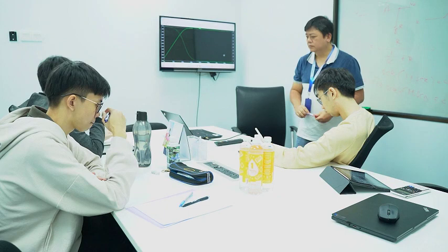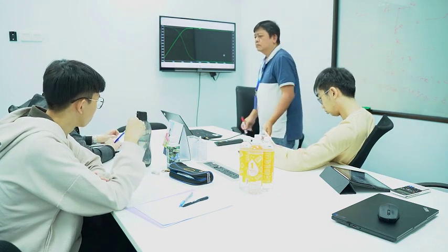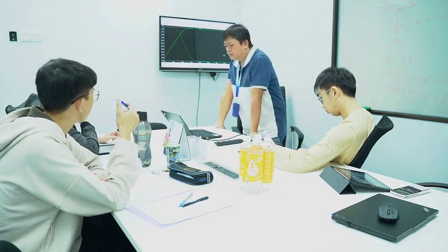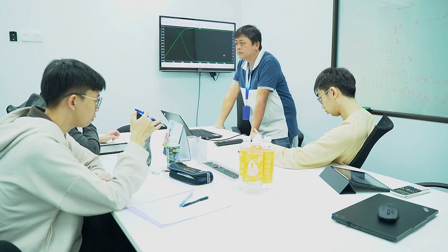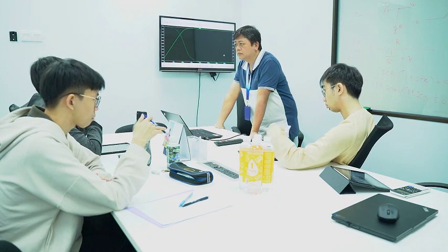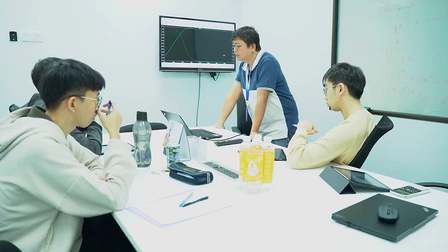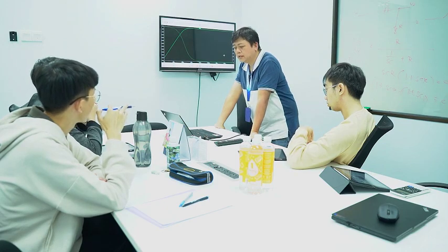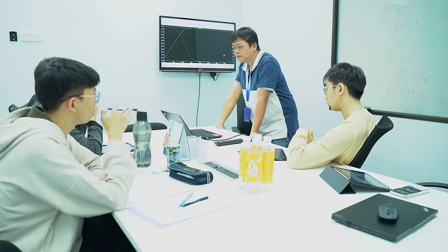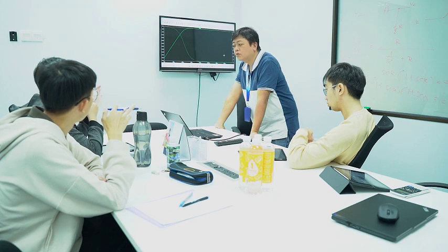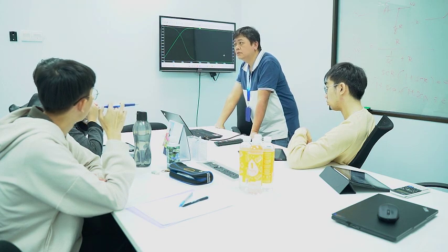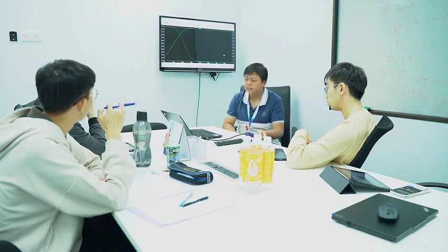One question. Back then during the low pass filter, when we tried to do the simulation, the phase shift always starts at 90 degrees as well. 90 degrees also. After the cutoff frequency, it will start to decrease. No, it starts from 0. The phase shift starts from 0, so you compare, it starts from 0.